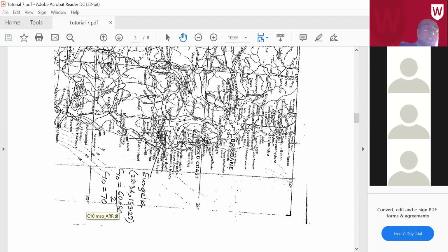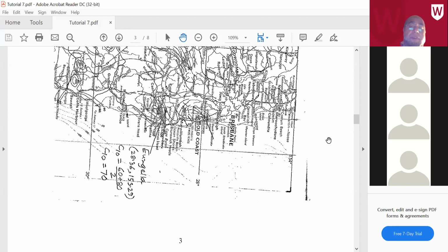This is one of the problems with this technique: you can see the density of the control lines is not that high. And when you want to do interpolation, there is a lot of uncertainty there. Drawing this contour map also has a lot of uncertainty, and then there is another level of uncertainty in interpolation as well. Different people will come up with different answers, because it is a bit subjective whether it's in the middle or at a third or something. So all this makes this technique a little bit subjective.